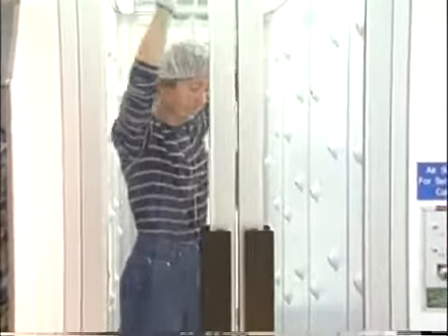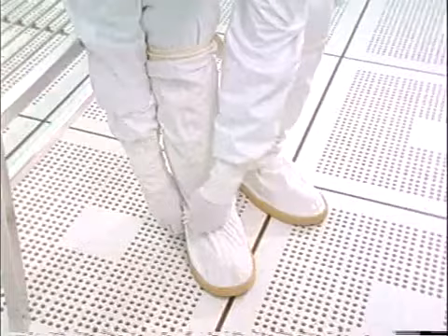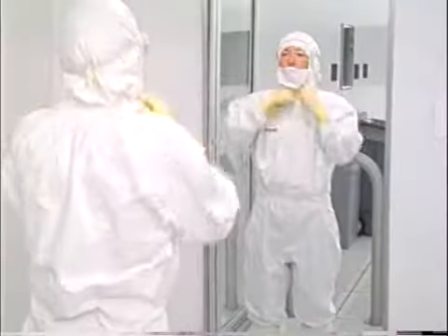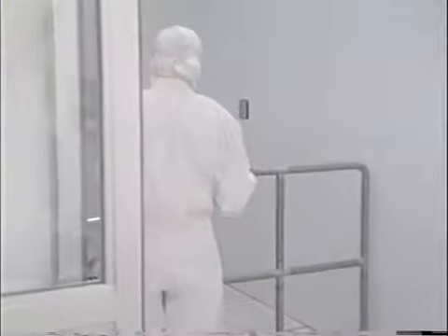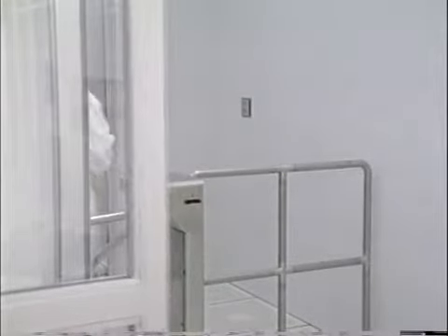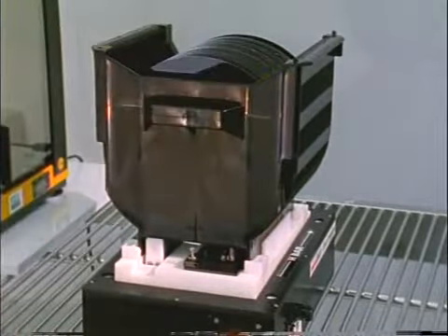To have a successful run, control of contamination is extremely important. It takes just a few microscopic dust particles to drastically reduce the yield of effective semiconductor devices. The equipment, gases, and chemicals that come in contact with the silicon wafers must also be of the highest purity and free of contamination. To start CMOS fabrication, P-type wafers with a specific resistance are selected.